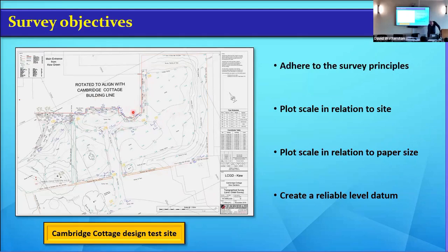But anyway, this is the survey. And again, if you go in and look at Scan to Go on the Dropbox, you pick it up, there's a little batch routine. You can either go in for your PC or go in for your Mac, and then you can actually look at the scan data. And all you can do is, there's all little globes or little circles everywhere where the scanner was set up. And if you go and occupy that, you can actually see what we're looking at, and you can zoom on it and you can take out distances of anything. And it'd be interesting to see if you come up with pretty close to 1.61 on that, which I'm pretty sure you should do. So it's good tools.